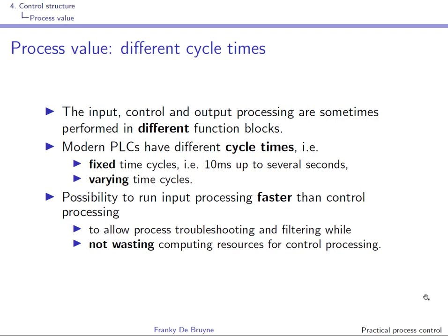This is of course required to run the difference equations that will, for instance, implement a first order or PID relation. As you can imagine from the name, blocks implemented in a varying time cycle will run at an irregular pace and are not suited to implement recurrent type equations, but you can use them to implement, for instance, a static relation. In theory, it is also possible to implement a dynamical system using a varying time cycle. This means that you have to keep track of the time that has passed since the last time the block was processed, and this makes things a little bit more difficult.